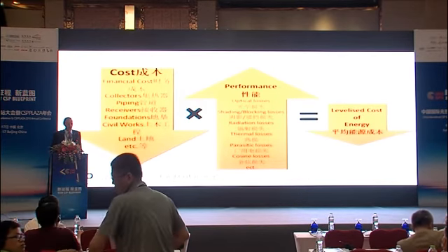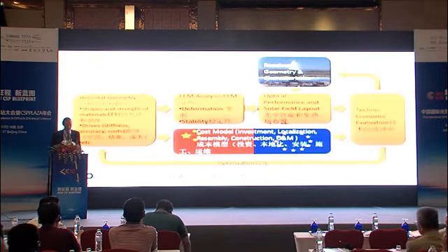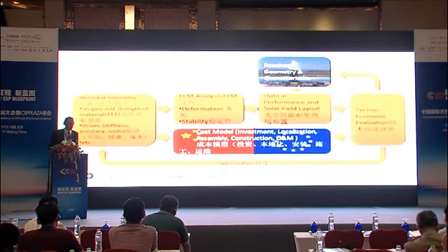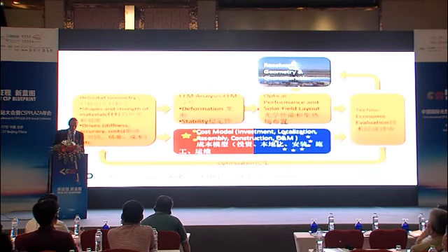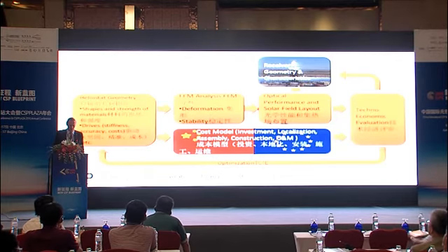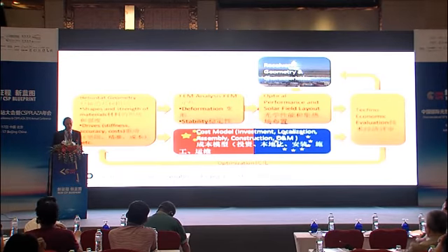Both of them are crucial to get the levelized cost of energy down. If you develop a technology, the techno-economic approach for a heliostat system goes over the geometry definition, loads of analysis on deflection, stability, and optical performance, and at the same time you have a rather large cost model in which you can see if the cost of the structure or the elements inside the structure, like drives or receivers, increase or decrease.